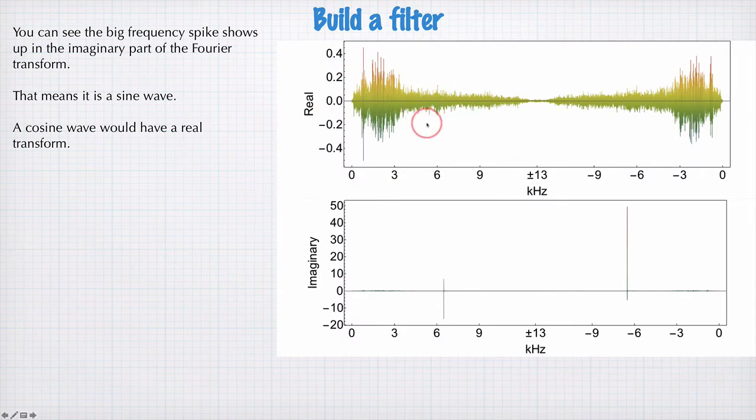Let's look at the straight Fourier transform of our audio file now, because we're not going to filter the spectrum, we need to filter the actual Fourier data. Because if you remember our LTI system, we have the Fourier spectrum going in, and we're going to multiply it by some filter function or transfer function, g of omega, to get our output. So now we've got to design our filter.